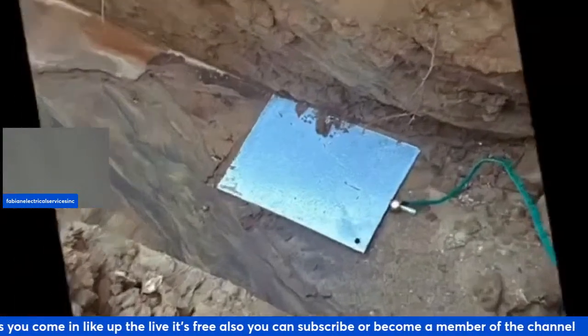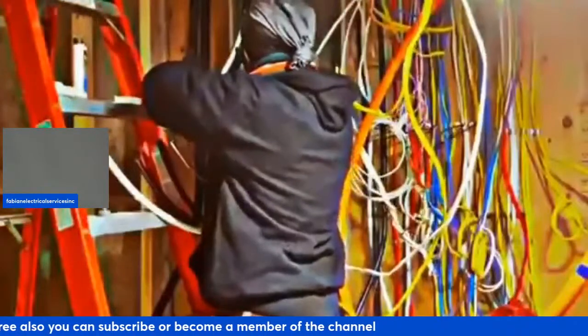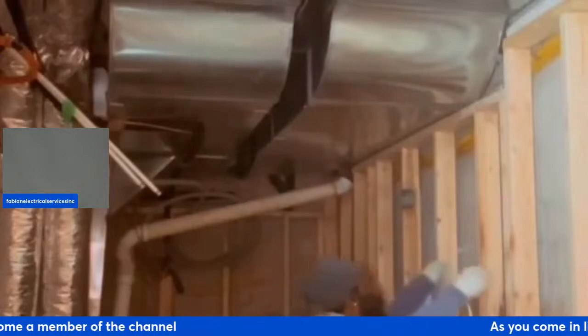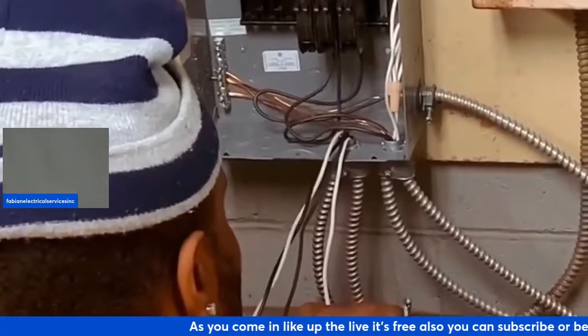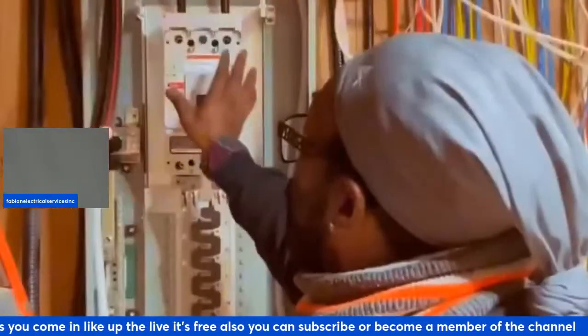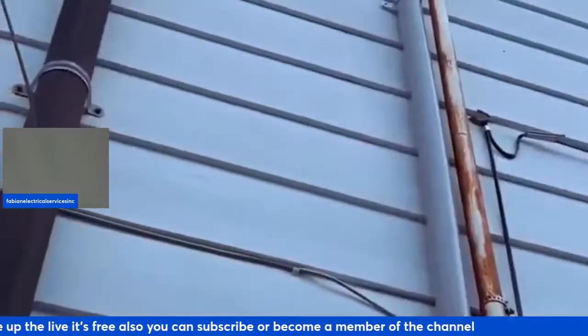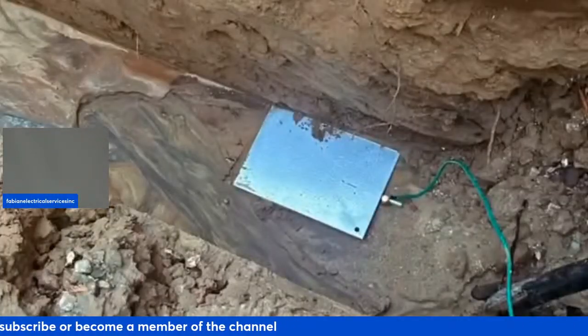So again, an AFCI is a product that is designed to detect a wide range of arcing electrical faults to help reduce the electrical system from being an ignition source of fire. Overcurrent protection devices do not detect low-level hazards or arcing currents that have the potential to initiate electrical fires.